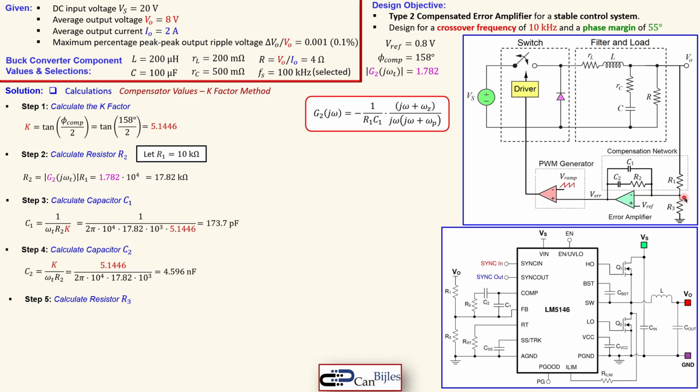in order to compare that voltage node with the V reference. So it means actually following that V reference over VO is R3 over R1 plus R3. So we can also say cross multiplication like so, and also in this form. So we can now express the R3 in the other parameters, which is given here. We know what the reference voltage is, which is 0.8. We know what our VO is, which is 8, from our specifications. So just substituting values here, we get 1.111 kilo ohms, so 1.11 kilo ohms approximately.